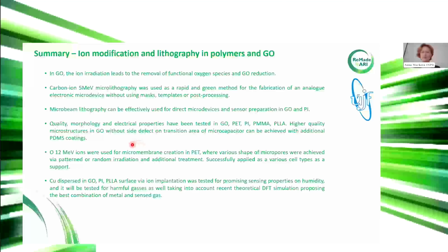And we also tested oxygen ions and used them for preparation of various shapes of micropores. It means that we tested what parameters and fluences can be used and what afterwards procedures can be applied to achieve the shapes most appropriate for applications such as cell sorting. In this case, we were able to prepare different shapes of pores.